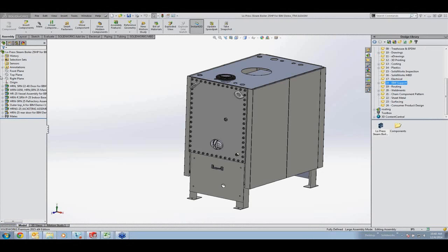Now in the case of a butt weld, I'm going to go ahead and change this from weld geometry to weld path and just select an edge here. I can select any edge I want to create a weld path. So in that case, the butt weld, I can also choose the edges of this gusset here. And it doesn't matter that there is a gap here. It'll still create the weld path for me. Now you can also use something more complex, like a sketch, for example, if you have a really complicated weld, and it will create a weld bead along that sketch.